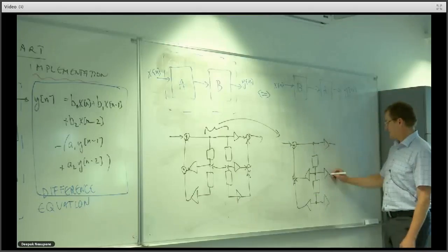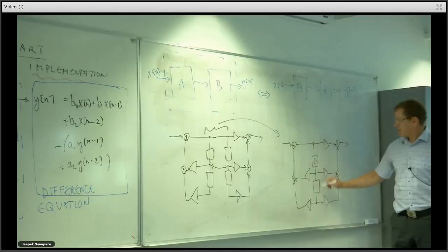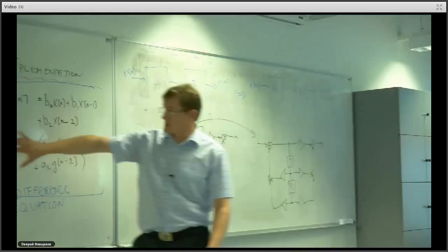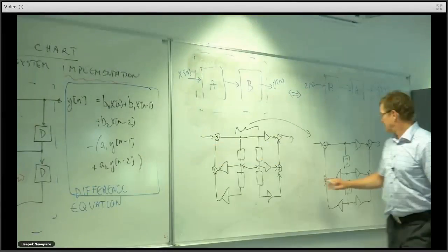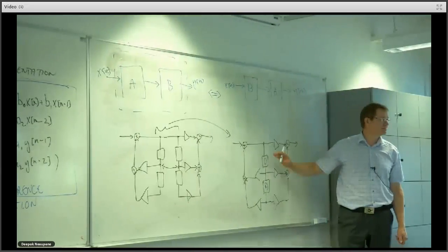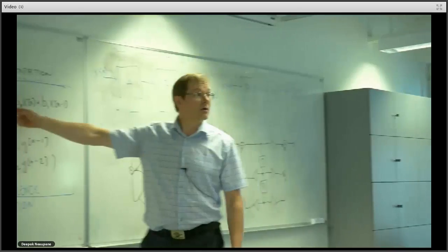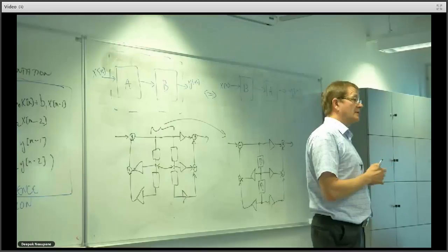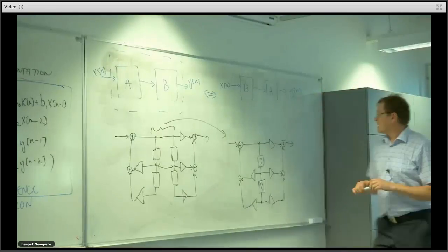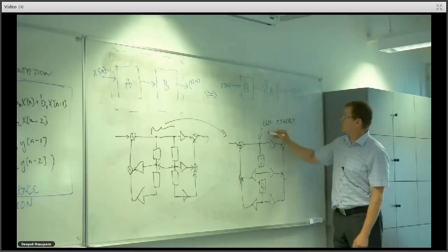All right. Basically, the system fundamentally looks like this after the modification. And while this system uses 4 memory locations to store intermediate data, this uses just half of the amount, so half the memory requirement. Think of now a system which has, say, hundreds of points here. You really start saving some space, especially on small microcontrollers. Okay, so less memory required.